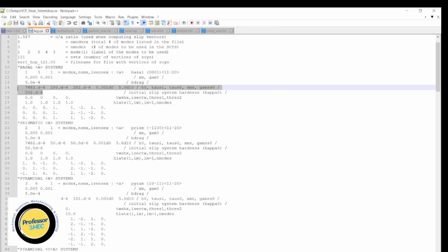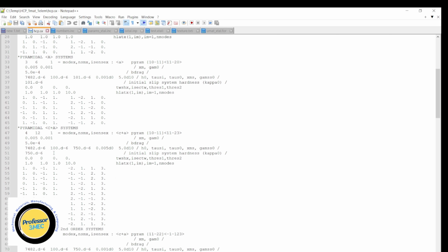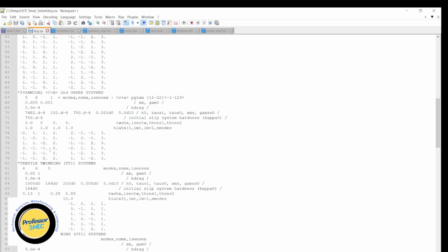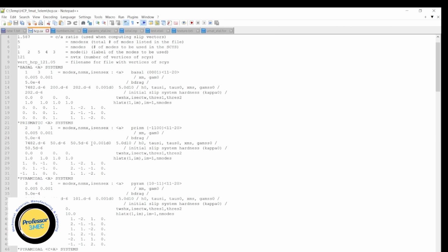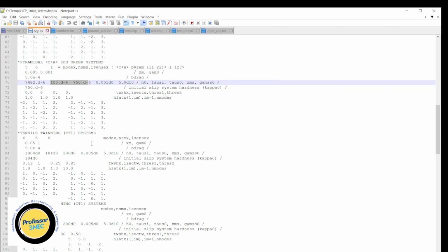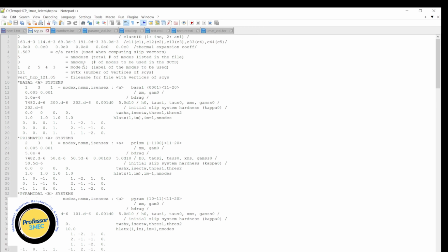So again, if you look at the theory first PDF file, which I will upload, then you will understand more about these parameters. The hardening law is slightly different than what you found in Bassani and Wu model and also Penn model. Similarly, for the second case also, we have the same set of parameters as the third also. So all of them have same hardening models, but parameters can be different, and you can see they are different in different cases. So this is how you define the parameters. You have to start with some initial guess, and then you have to run the simulation.